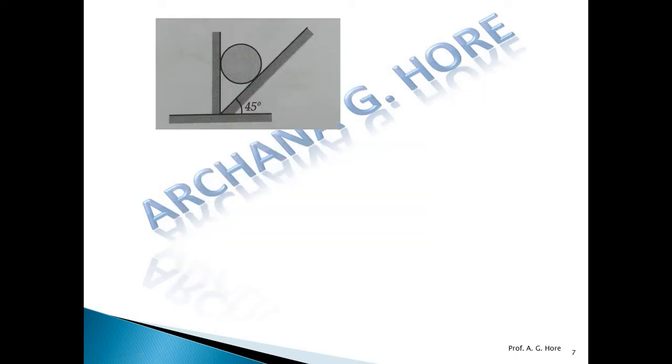Now here sphere FBD, first this surface is vertical, so suppose this point is A, so reaction is horizontal and RA is the reaction. Okay, this surface is a vertical surface, that's why this reaction is horizontal, perpendicular to the surface, arrow is towards the surface.